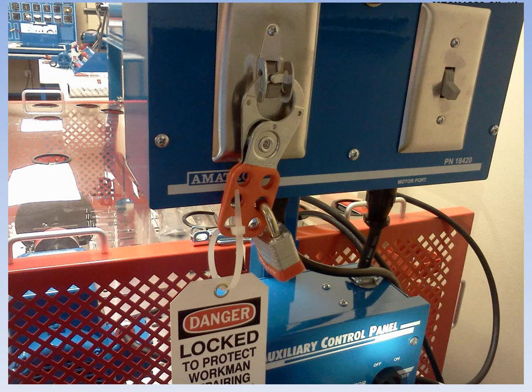So for us in our lab, we're going to simulate that every time we work on a motor and we do our belt drive, our chain drive, and our gear drive in here. We are going to do lockout tag out. Now, I'm not going to make you go through with the full tag out. You don't need to write everything down on it. But when you guys are working in groups, you're going to put the hasp on. That's the clip there with the red handles that the lock is going through, and you're going to put a master lock on there. And each one of you will have a lock.